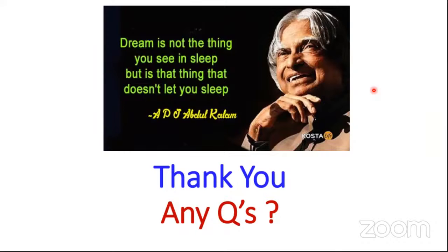quick solidification, right? If we use, let's say, 100 microns in one layer to melt them, obviously your laser beam or the electron beam will not be able to penetrate the entire thickness, right? Then apparently you'll be ending up in improper melting.